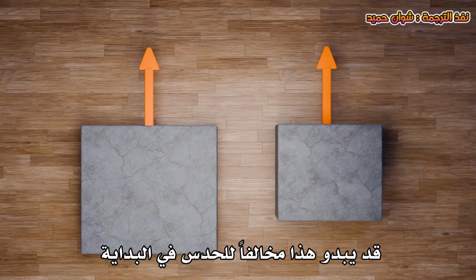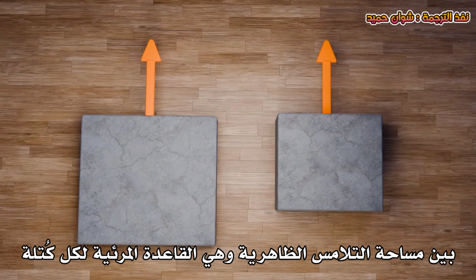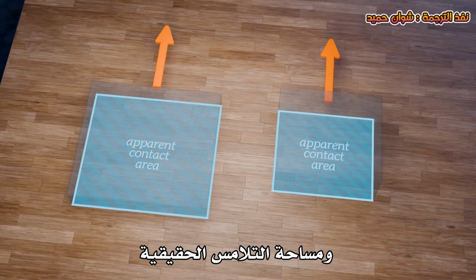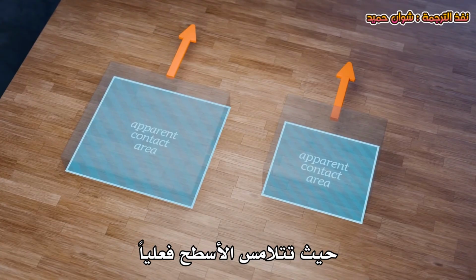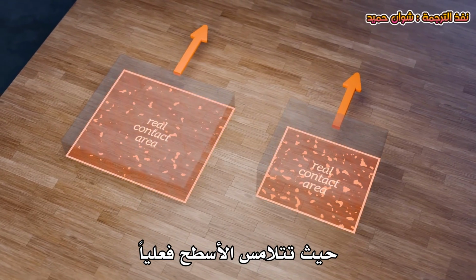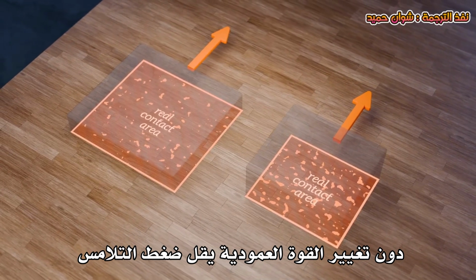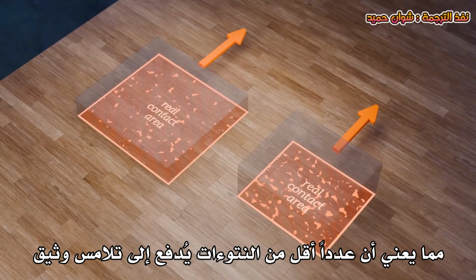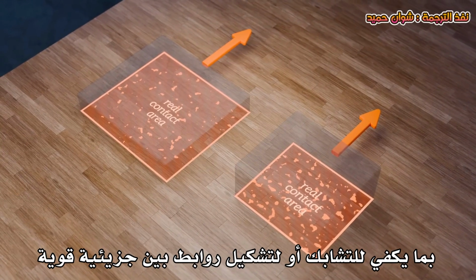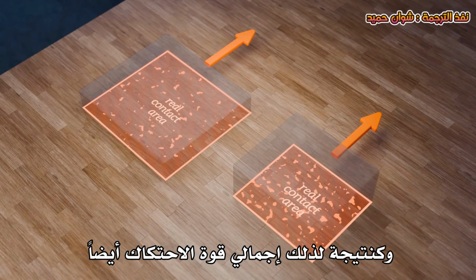This can feel counterintuitive at first, but makes sense when you think about the difference between the apparent contact area, which is the visible base of each block, and the real contact area, which is the sum of the microscopic contact points where the surfaces actually touch. When you increase the apparent contact area without changing the normal force, the contact pressure at the touching asperities decreases, meaning fewer asperities are pushed into close enough contact to interlock or form strong intermolecular bonds. The real contact area stays roughly the same, and as a result, so does the total frictional force.